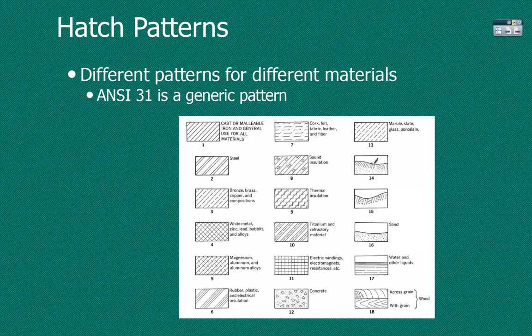This hatch pattern is in AutoCAD. All these ones are in AutoCAD. If you go to the hatch command in AutoCAD, you're going to see all these patterns and more. That shows us it's earth, and usually they don't hatch everything, they just hatch the top little bit. Same thing if you're doing stuff that's wood. And here's concrete, which you might also use in architecture.